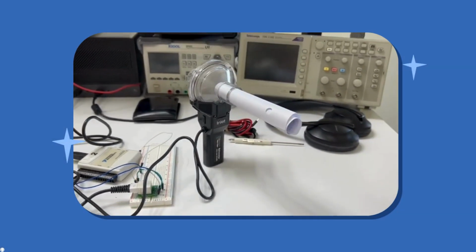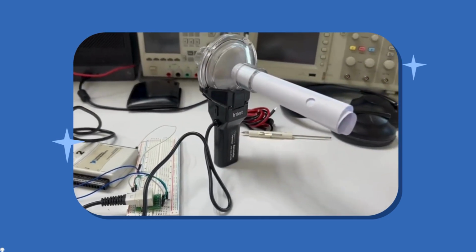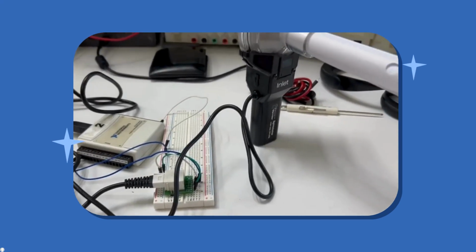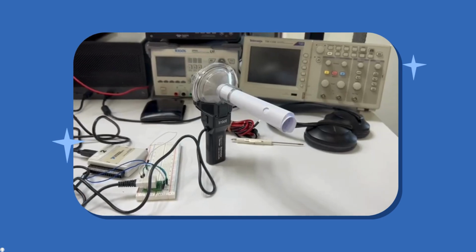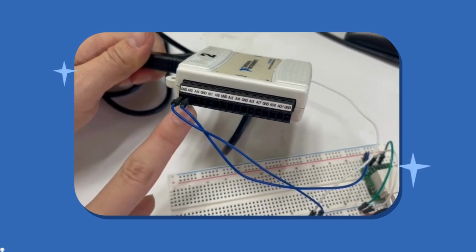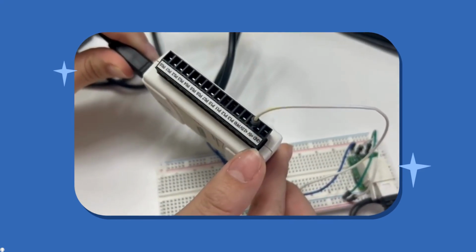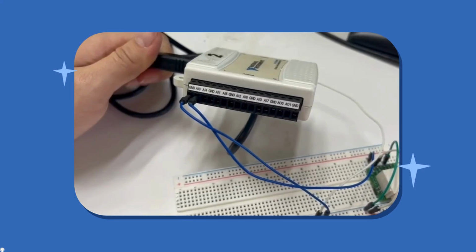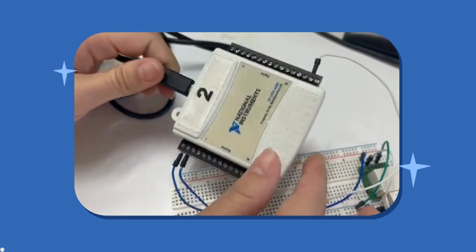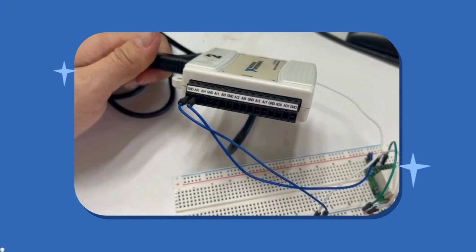with a piece of paper inserted in the mouthpiece for hygiene reasons, connected to a protoboard using an analog protoboard adapter, or BTA connector, and this in turn connects to a NI USB-6009 data acquisition card from National Instruments. Jumper wires are used to connect the output of the BTA to analog input port 0 of the data acquisition card, along with the ground connection to ensure a common reference. It is important to provide the necessary power to the BTA, which involves connecting a jumper wire to the 5-volt supply available on the National Instruments card.